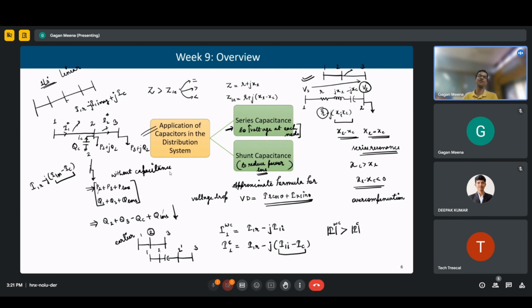Since such a high voltage is there, we have to take all the safety measures and precautions. Before doing any kind of maintenance, the line is always de-energized. First the circuit breaker is opened, then the isolators are opened, then both sides of the line are grounded, and whatever charge is there goes through the ground. Then the maintenance work or whatever upgradation is required is carried out.